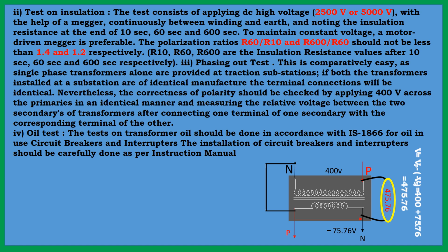So it is made to withstand for 10 to 15 minutes, and if it does not break, then again raise the voltage with the auto transformer. Where it breaks, that is the value. Take some readings, 5 to 10, and take the average. That will be the breakdown voltage value of the transformer. For new oil, it is better to keep it at 60 kV breakdown voltage.